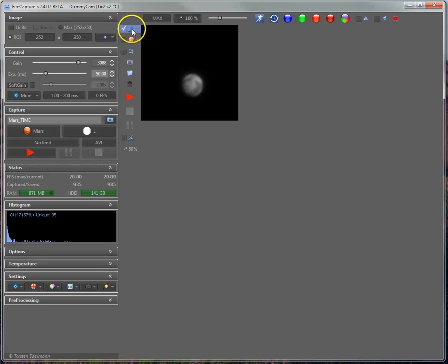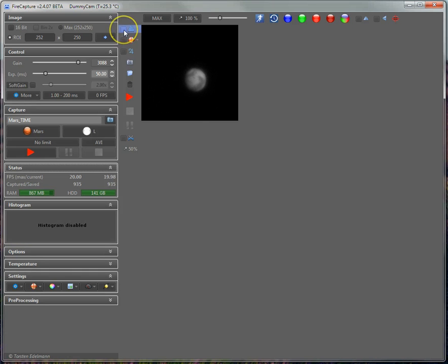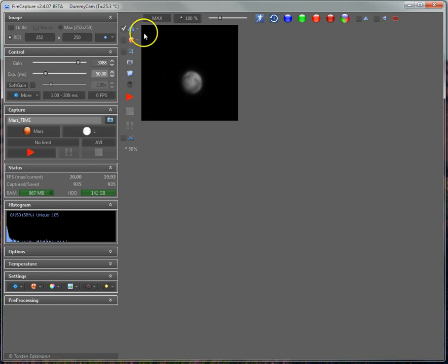There are some more options regarding the histogram. This option over here in the toolbar is the histogram. By default it should be disabled; it should be enabled. You can jump to the histogram settings just by clicking that small triangle over here and clicking on options.